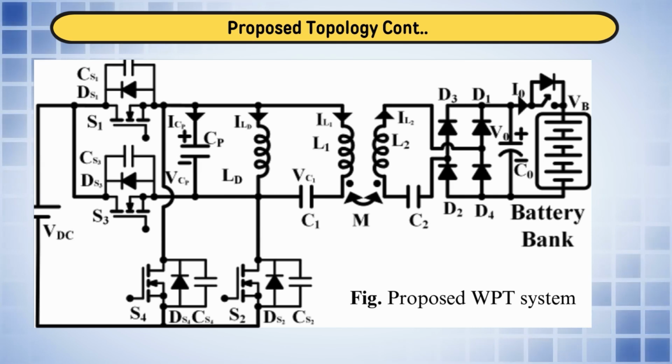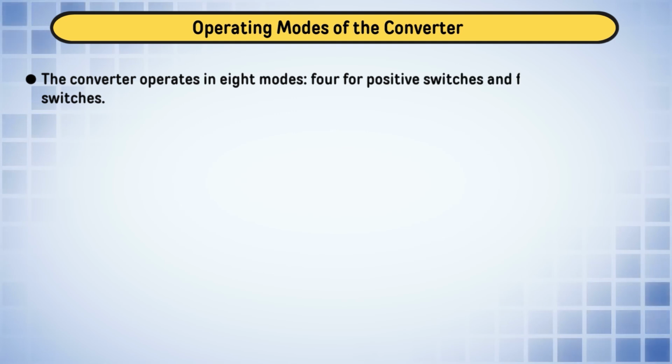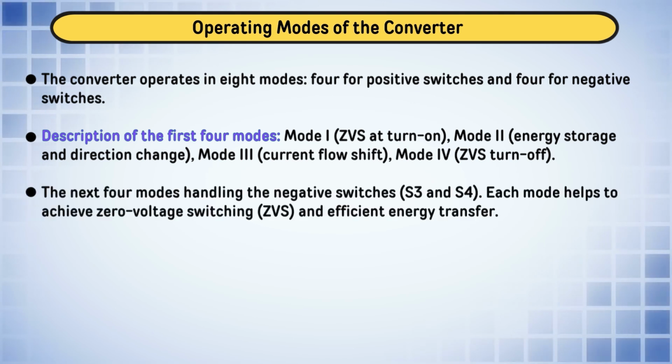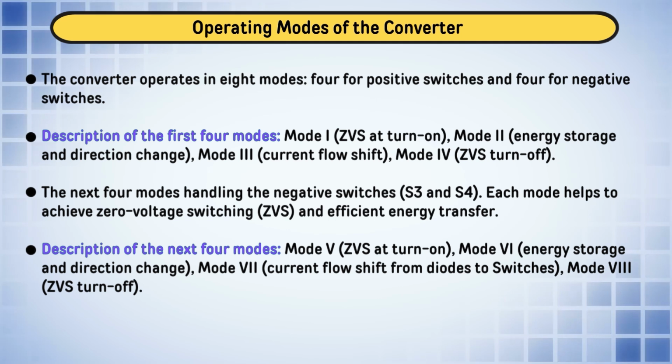And similarly, we have power flow analysis here. On the primary side we have given the voltage equations, and using this phase difference we are able to derive the inductor current, which is the voltage difference divided by impedance, and then we have complex power transfer, active power transfer, and what would be the maximum power transfer under these conditions. What are the conditions when phi is 90 degrees, or phi is at some particular angle. So, hence maximum power transfer,